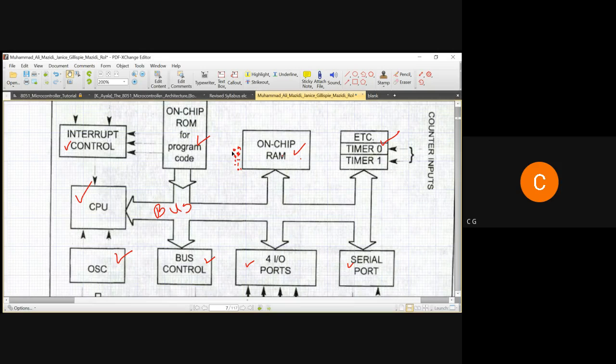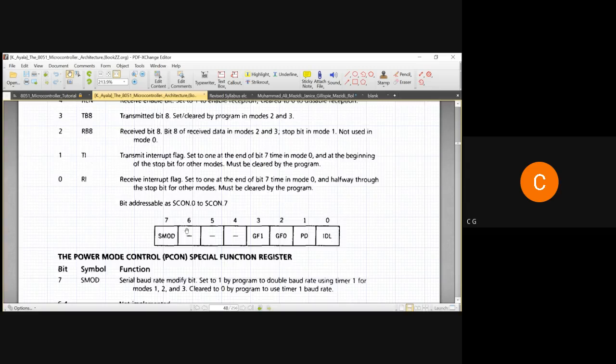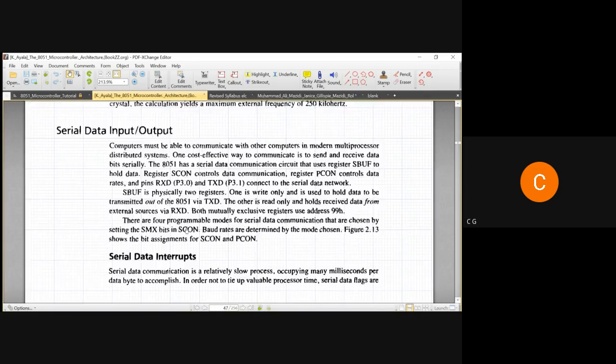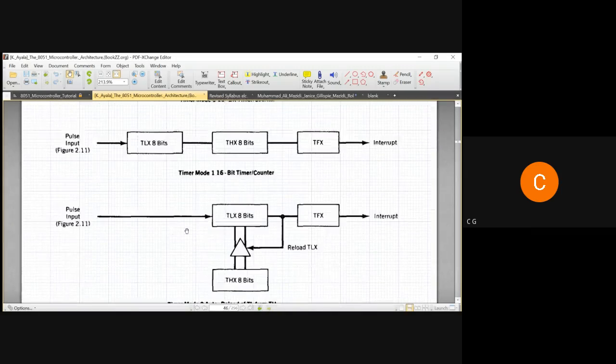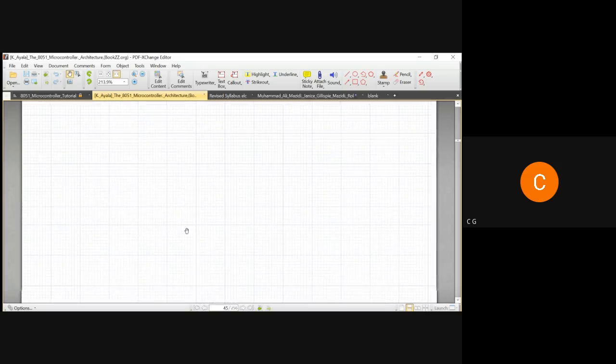So you will have locations from 00 up to FF for 128 bytes of RAM. Not 2 raised to 128. Only these locations are available, 00 to this, and all these locations are divided into different parts. Let me bring it here and show how they are divided.